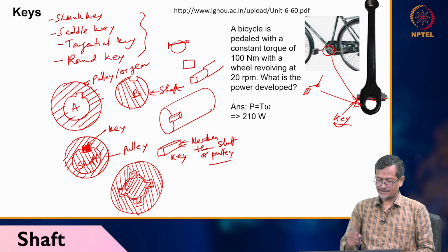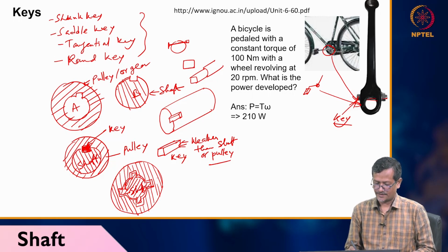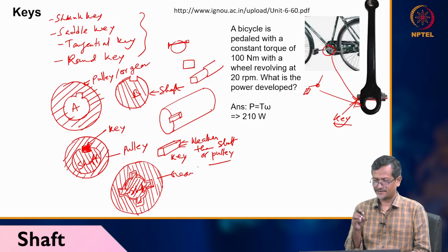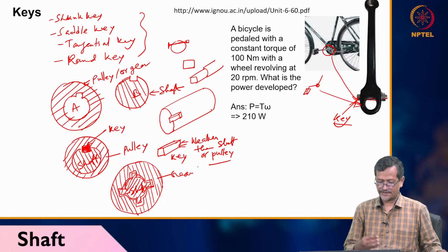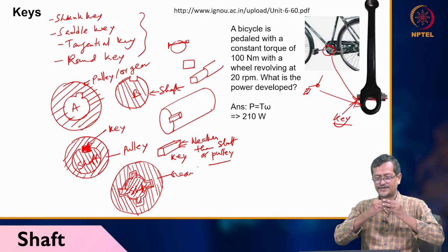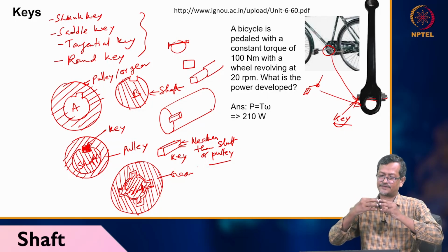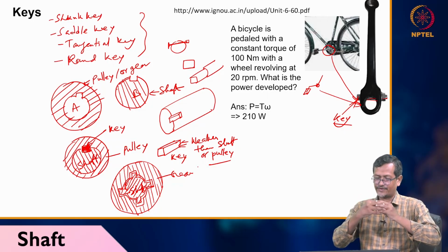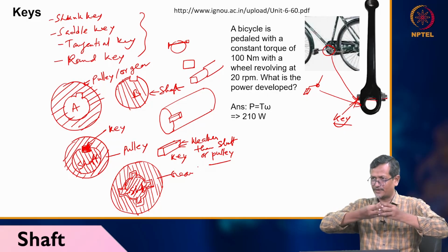Okay, so you can see, if the shaft is rotating, the gear also will be rotating. So there is no extra key you are inserting, rather you are giving one spline. So it is like this: you have one shaft and you have one pulley and you are inserting it and this teeth-like structure will be fixed here, and when you are rotating, both will be rotating together.